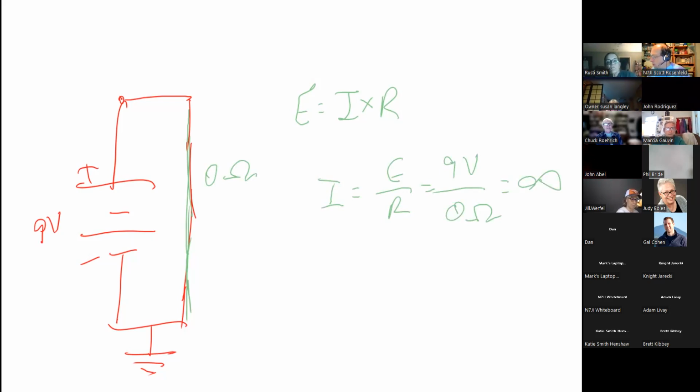Now, remembering, of course, that that's not really a short circuit. That's a poor little diode sitting there. It's going to have this massive amount of current flowing through it. So what's going to happen to the diode? It's going to work for a very, very short period of time, then self-destruct. So what you're going to do is throw a resistor in series with it to actually give the circuit a little bit of resistance, because once that diode turns on, it becomes a short circuit. So the resistor is there to provide a stable bias current and protect the diode from committing suicide.